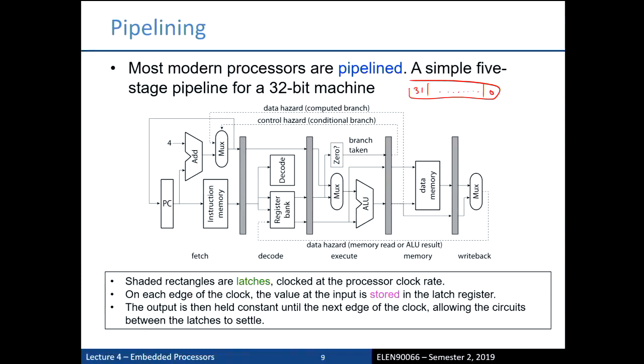And that means that the program counter, which points to the next instruction, increases by 4 bytes at a time. We normally store things in bytes, so 32 bits is 4 bytes, 8 by 4, and then every instruction that executes, the program counter skips ahead 32 bits, or 4 bytes, to grab the next instruction.